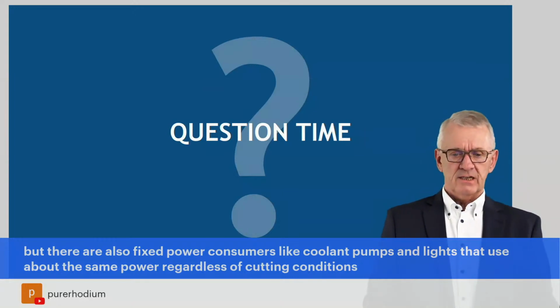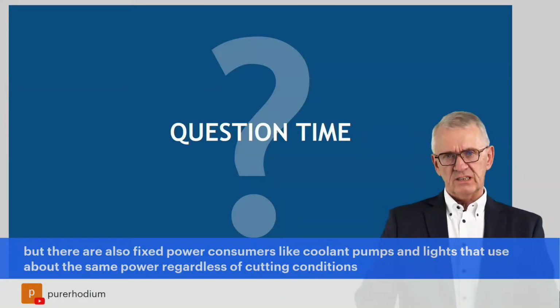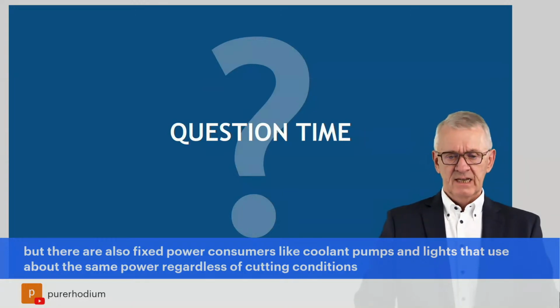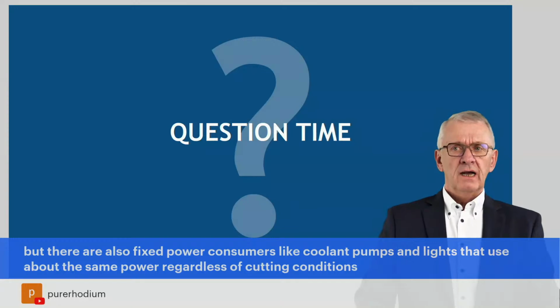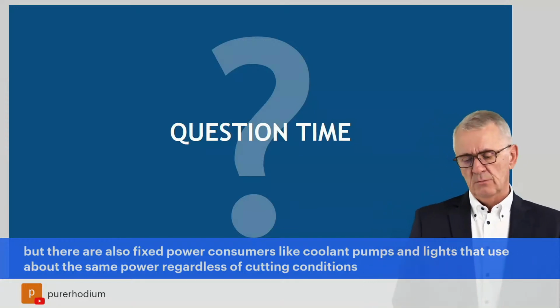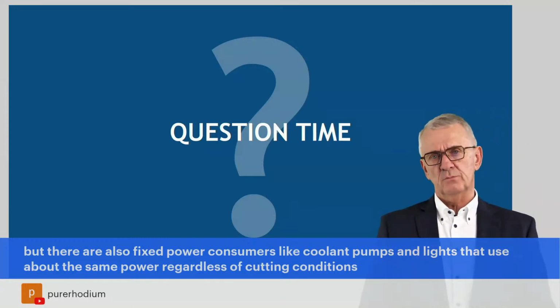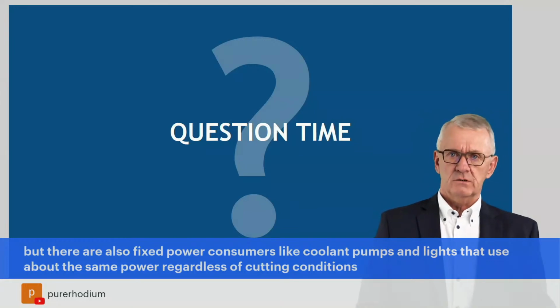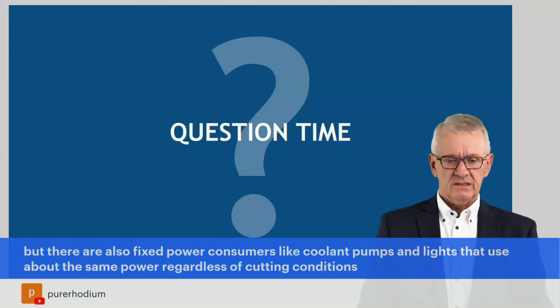The time is too limited to give you the full picture, but in general, if you are confronted with high energy costs and you worry about extra power, extra energy needed for cooling pumps and stuff like that, which basically should be in the equation for the machine hourly rate, the correct combination is that you have to increase feeds and depths of cut within what is possible. I know there are mechanical limits, but within what is possible, you should go for bigger depths of cut, bigger feed, and combine that with lower cutting speeds. That's the way of thinking that you should use in that situation.